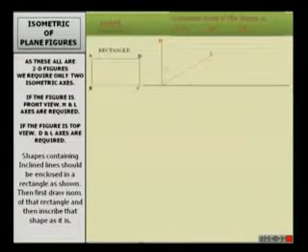To draw the front view, we require H and L. L will give us the length. So by drawing two lines, H and L, H is as usual 90 degrees to the baseline and L will be 30 degrees. Hence it is the isometric axis.